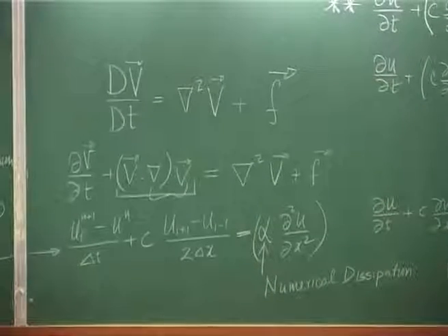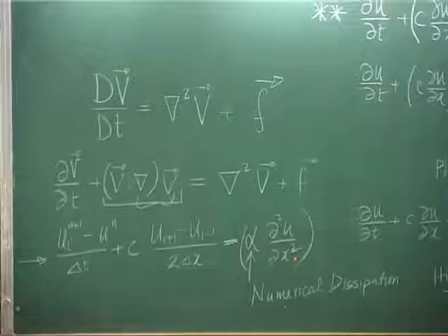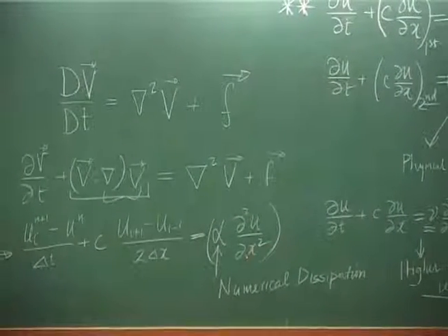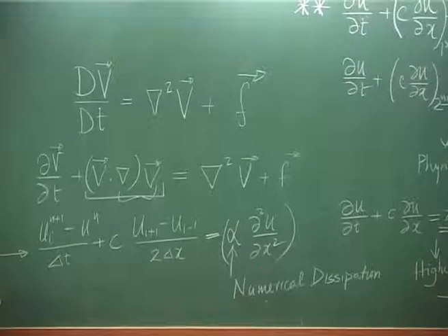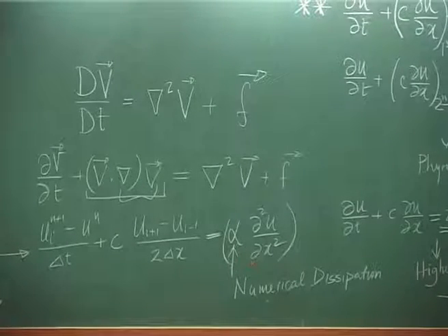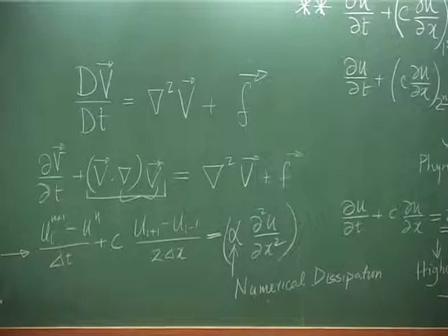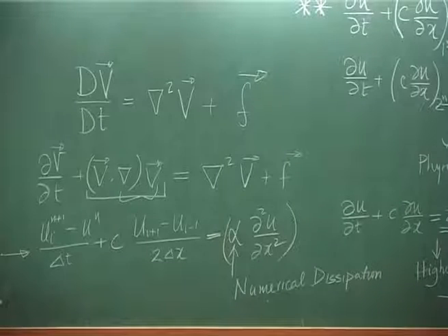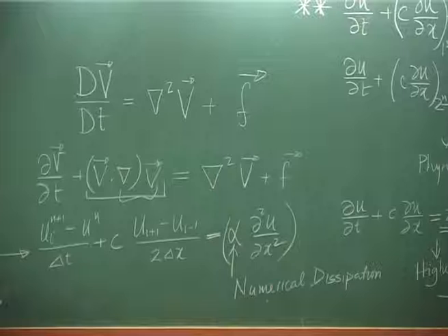So, you would have to add some kind of a dissipation. I would make the point that in most of the computing you do not like to add a second derivative term, because the physical dissipation always appears with the Laplacian operator, and that is the second derivative, right. So, we do not like to give a second derivative term, instead we would like to have a fourth derivative